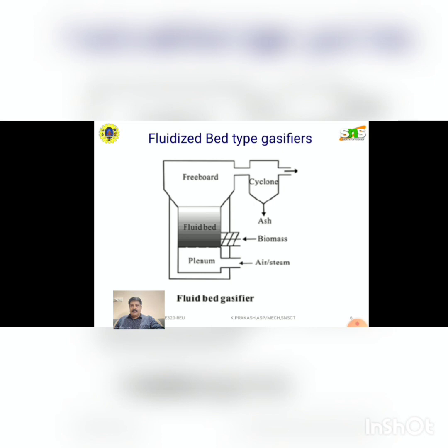The fluidized bed is initially heated externally close to the operating temperature. The bed material, usually sand, absorbs and stores the heat while the turbulence and mixing of the bed keeps the temperature very uniform throughout the bed. When biomass fuel is introduced into the fluidized bed, the high heat and mass transfer characteristics permit rapid energy conversion at a nearly isothermal condition.